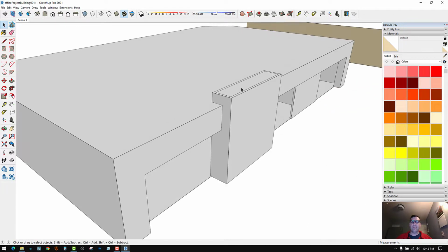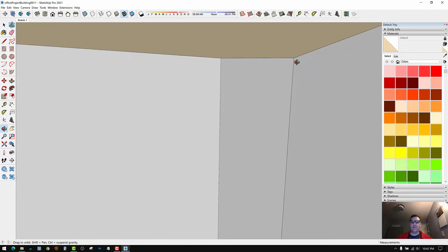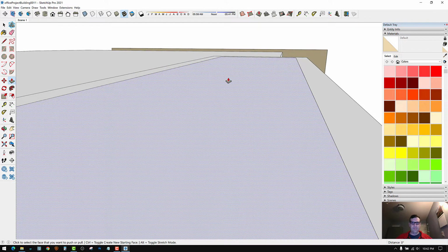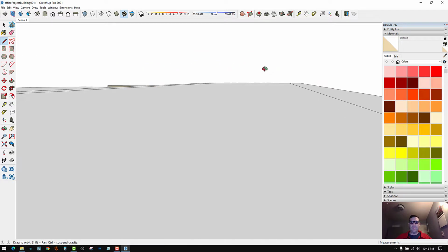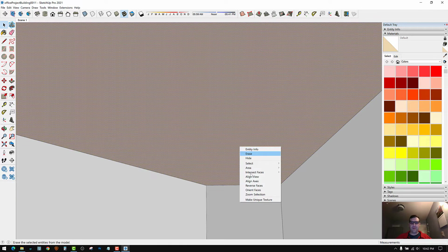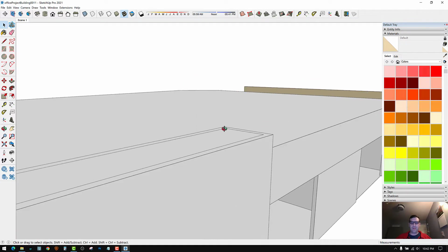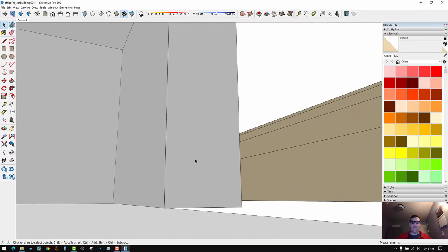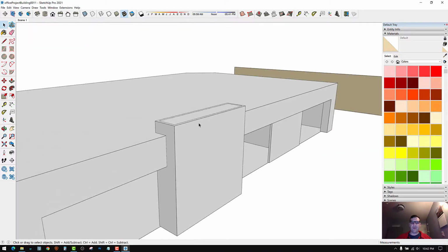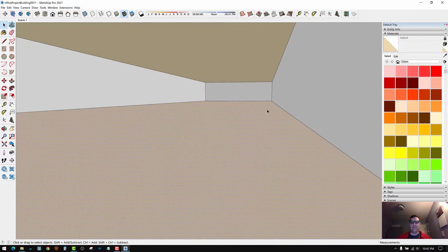That looks great. We'll do the same thing to this one. So go down 1 foot, create a roof plane, right click, reverse. And in reality this is just a fake wall too, just empty, so I don't even need to have a ceiling in this.